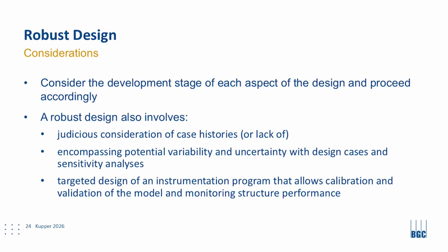Also, that you're encompassing the potential variability and the uncertainty with maybe more design cases, more sensitivity analysis, maybe with a slightly more conservative approach. And I'm not talking about something overly conservative. And you need a targeted design of an instrumentation program that allows for calibration and validation of the model and to monitor structural performance. Things like tailings dams, or dams, or slope stability, or load tests on foundations are good for that.